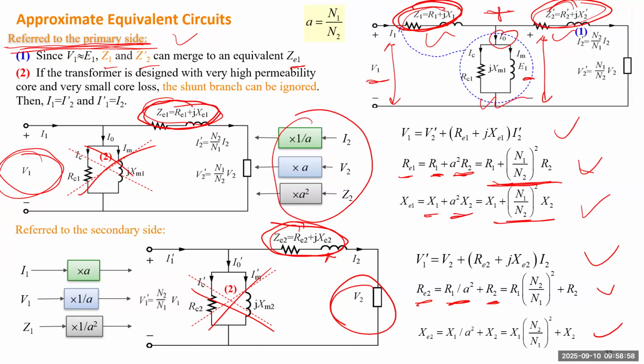If you define a base value, for instance, for the primary side you define 220 kV as the base value, any voltage will be divided by the base value, and you will get percentage of operation. Similarly, for the secondary winding, you have maybe 35 kV, and you also use that as base value. The percentage will be the same. Okay, so that will be addressed by the per unit system. Let's continue on Friday.